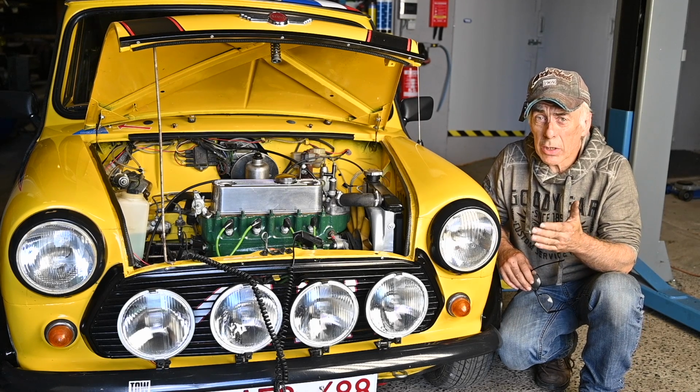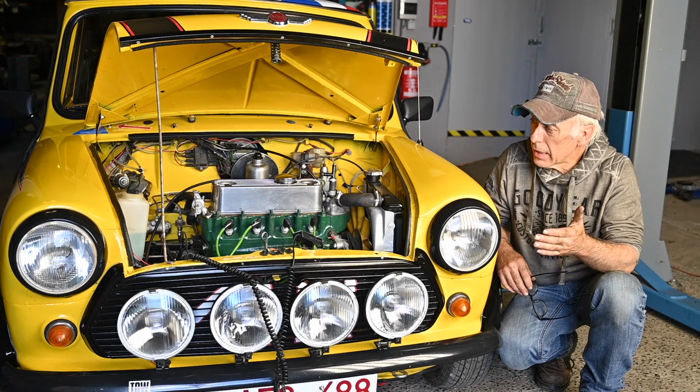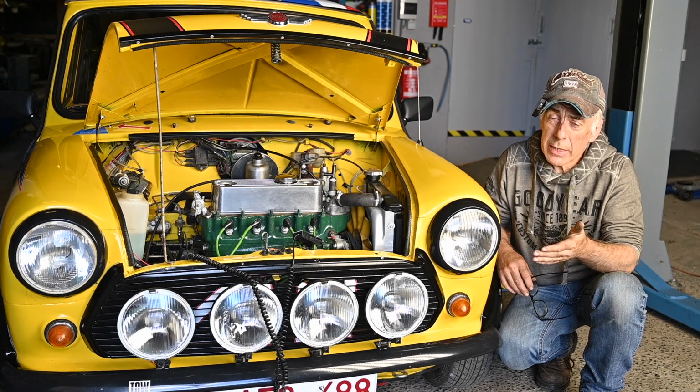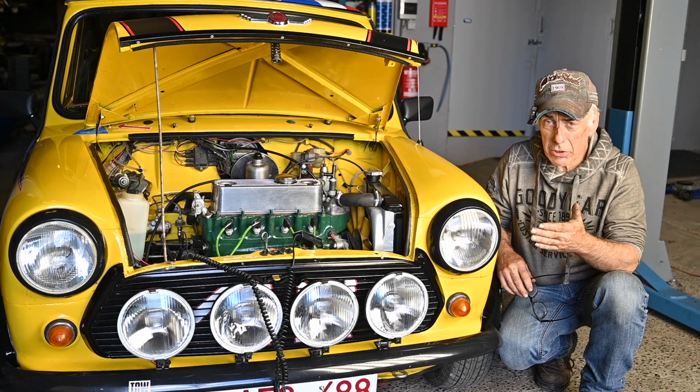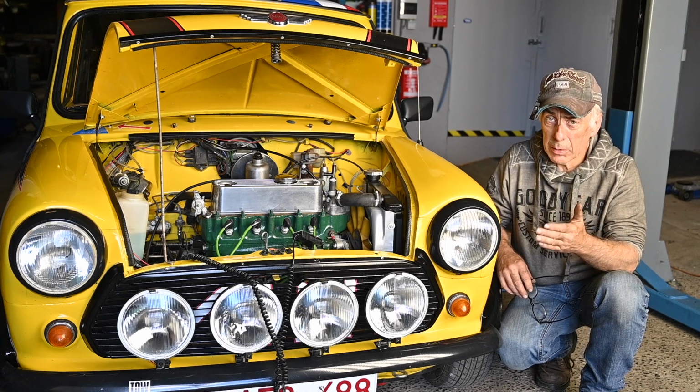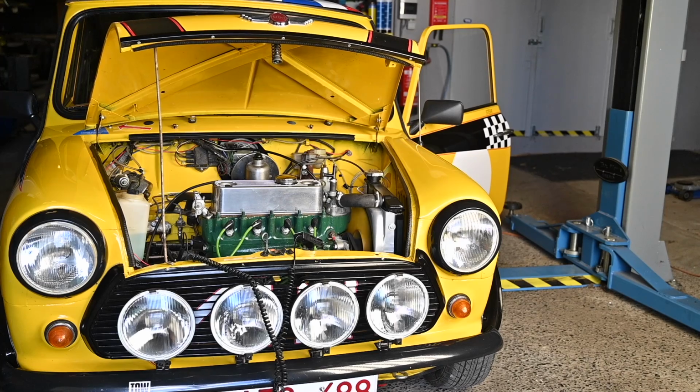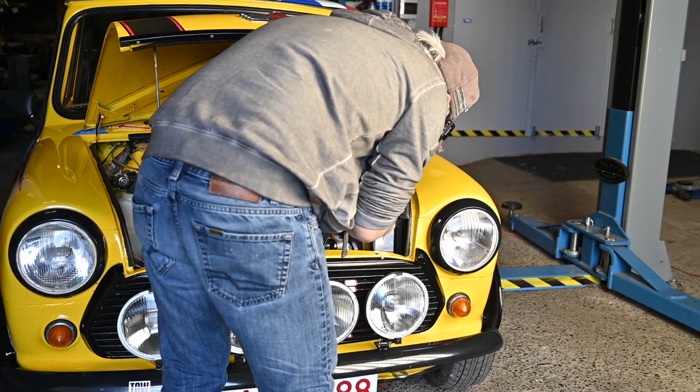Once you have rotated the distributor so that the marks on your pulley line up exactly on the amount of degrees that you want for your static advance, all you need to do is shut down the engine and tighten down that bolt and lock that distributor into place, and then start the engine again and do a double check if nothing moved. That still looks spot on.